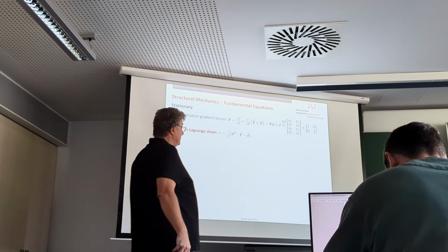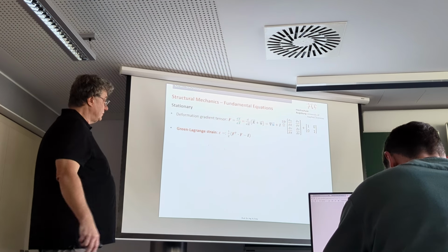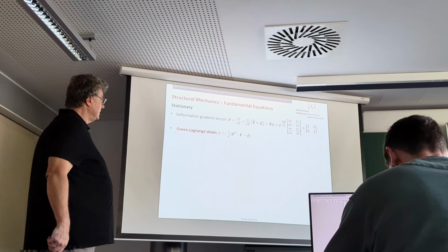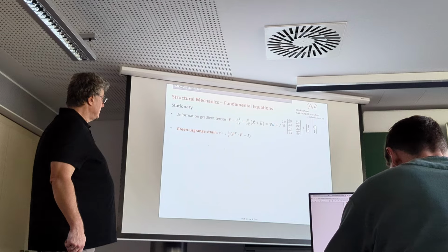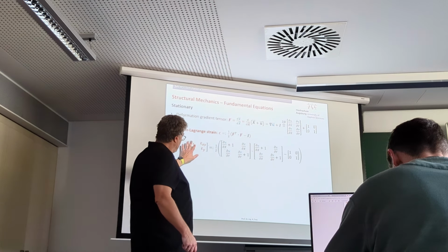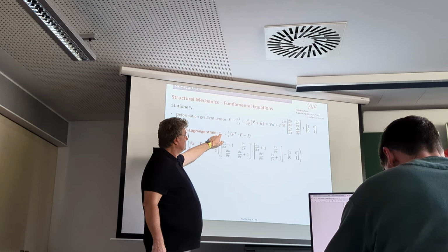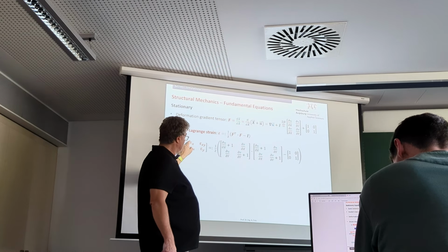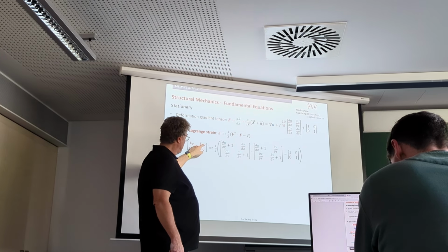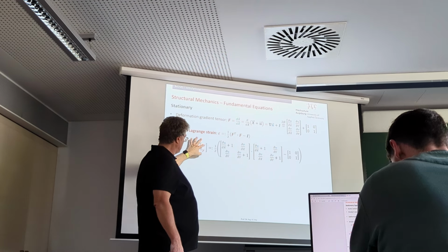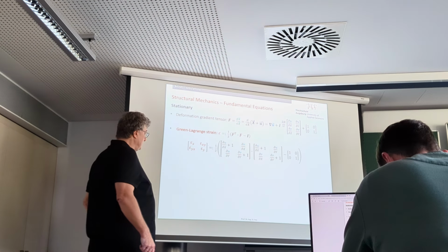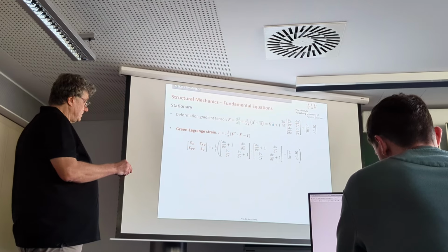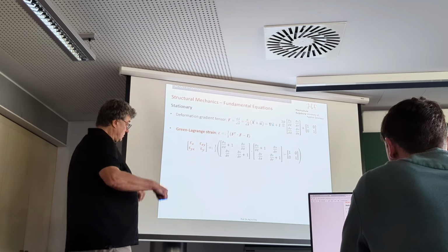Basically, we just have to make that operation. It means matrix multiplication. It would be useful to have MATLAB or some tool which does it analytically, then you don't miscalculate. Let's just do it. This is the strain matrix, or tensor would be more precise, with EX, EY, and the mixed elements. They are the same, that's why we just have 3 elements to calculate. And this is just the extensive way of writing what is written here, more confined.